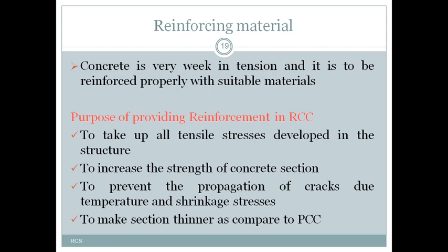The reinforcing material. Next ingredient is reinforcement. As we know, concrete is very weak in tension and it is to be reinforced properly with a suitable material. Then what is the purpose of providing reinforcement in reinforced cement concrete? The first and foremost purpose is to take up all the tensile stresses developed in the structure, to increase the strength of the concrete section, and to prevent the propagation of cracks due to variation in temperature and due to reduction in volume, that is shrinkage stresses.